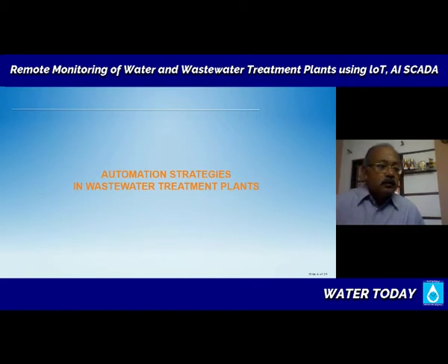Is there a question? Yeah, we see a question from Mr. Rajendra Kumar Jayachandran: can we use it in effluent water plants at chemical industries? Yes, sir. Excellent question. Actually, you can use these instruments in effluent treatment plants in the chemical industries. Only thing is you will have corrosive chemicals, possibly chemicals that can react with your sensor construction. So we take some special precautions while using it in the process industry, knowing the condition of your water.